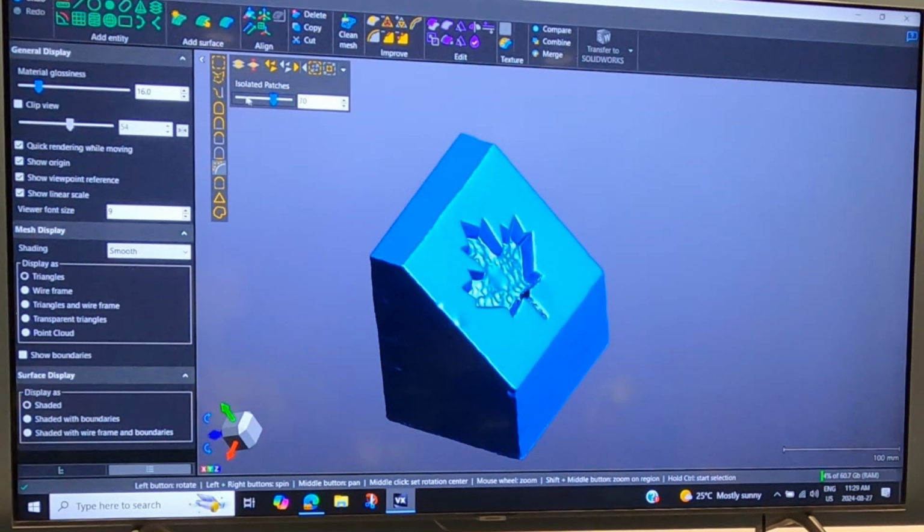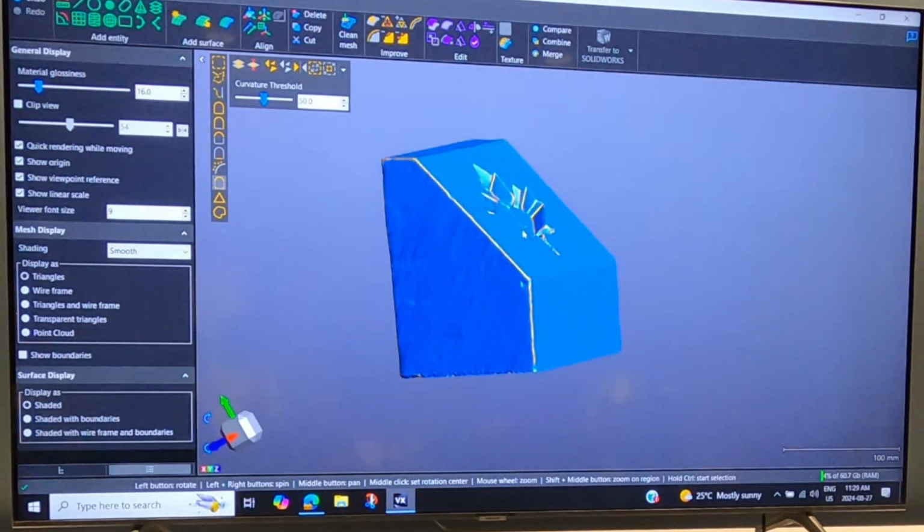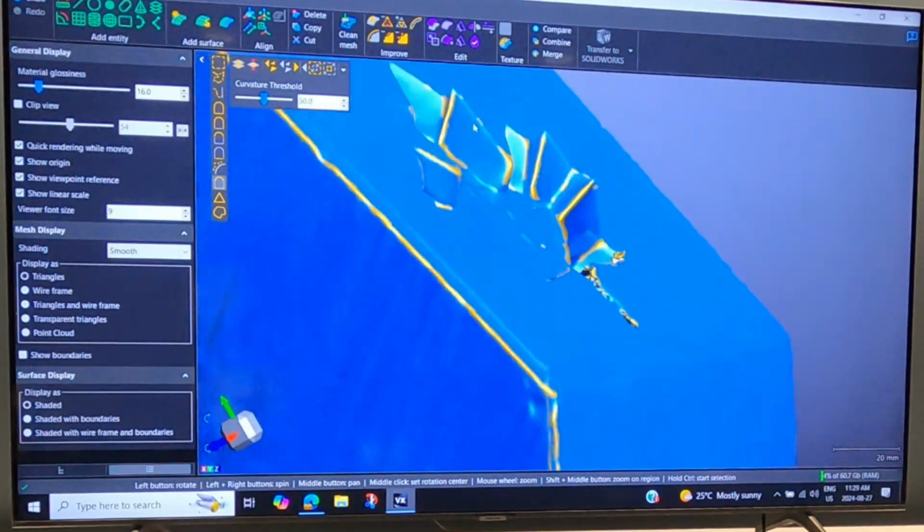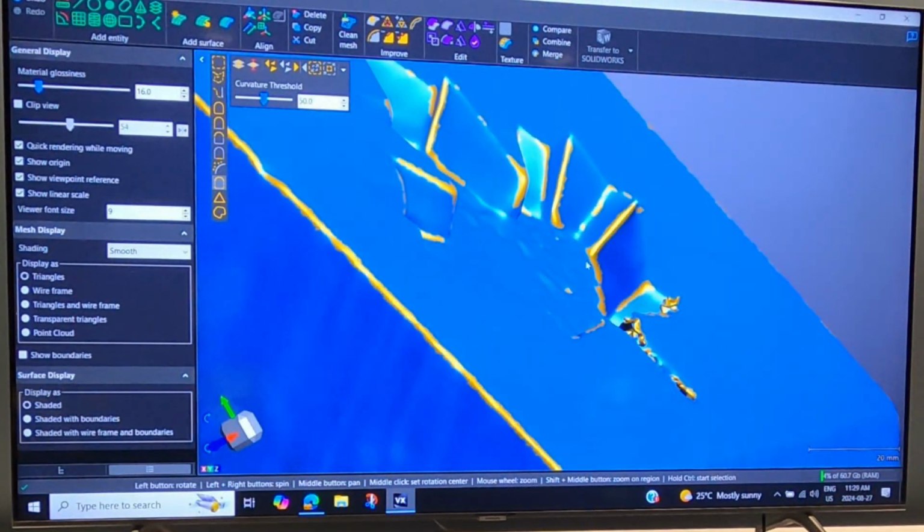We really don't use it a lot. So unconnected, basically. Yeah, floating. Then we have curvature selection, which really narrows it to edges. That's specifically selecting radiuses and corners and edges. Very rarely used, unless we want to maybe enhance.